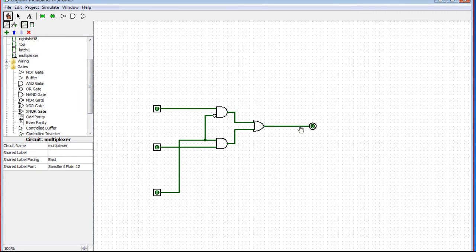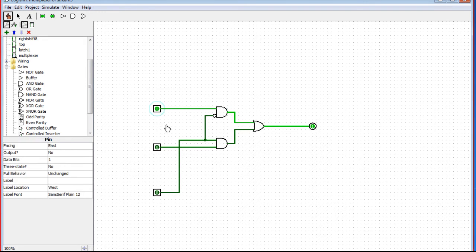Let's see here. All right. So you've got two inputs here, and you've got one selector. So we'll set one to 0 and one to 1. If the selector is 0, you're going to select the top one, and if it's 1, you're going to select the bottom one, right? Okay, let's select the bottom one here, and the top one. Now we're selecting the top one. This one doesn't care. That's a multiplexer. That's all it is. 3, or depending on how you're counting, 4 logic gates.